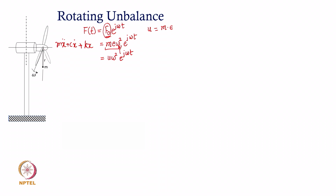So, for example, this would be epsilon, the position of the unbalanced mass m from the axis of rotation. This m multiplied by epsilon, that product itself is the unbalance, and there is a practical reason why it is usually clubbed together as a product. So, the unbalance has a unit of kg meter as the product of mass and the eccentricity epsilon.